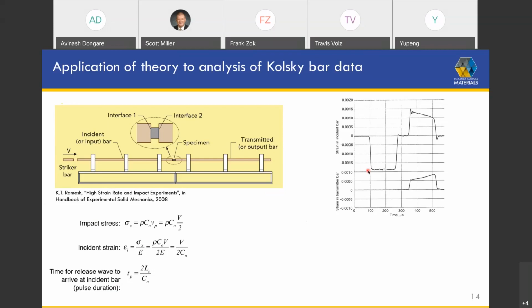Okay. So I think the question you're asking pertains to the mechanisms of inelasticity and the sensitivity of those mechanisms to strain rate. When you're at low strain rates in the creep domain, typically below about 10 to the minus 6 per second, the mechanisms will often involve diffusive processes.